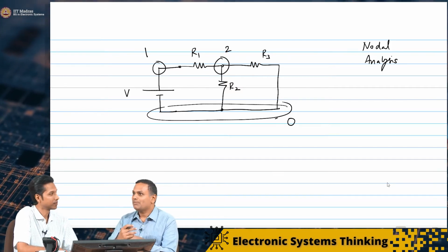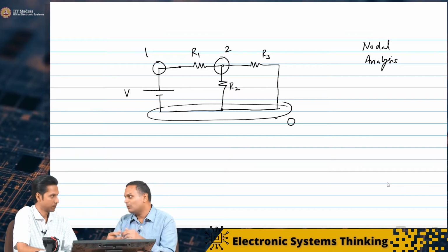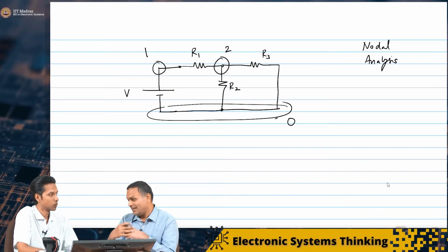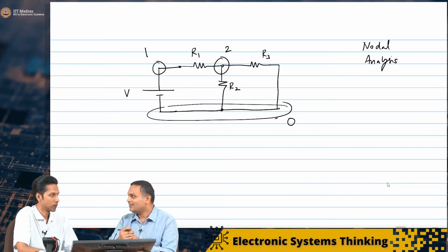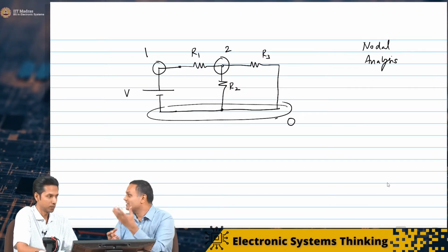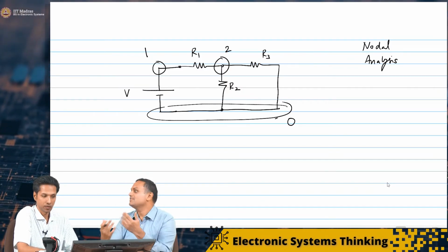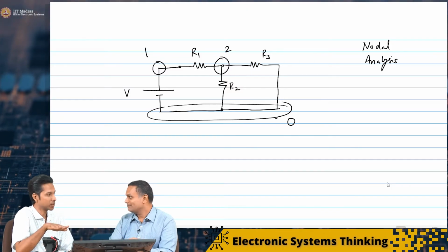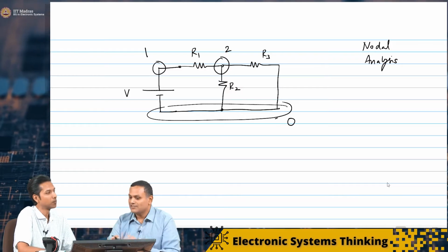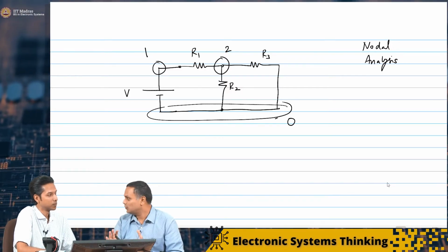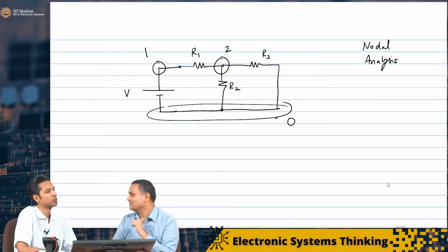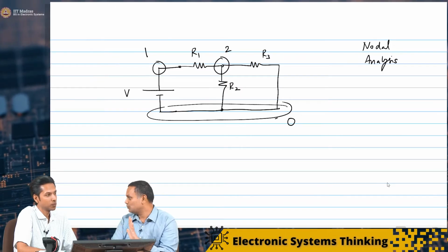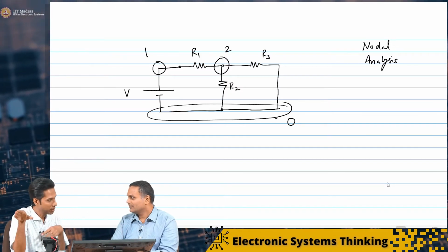Yes. So we saw that there were higher potential nodes and lower potential nodes, and if your potential increases at a particular point, that means that more positive charge is being added. If the potential decreases, charge is being removed. So our assumption is potential is staying the same, so the charge is constant. We are assuming that there is no net charge being pushed into node 2, and no net charge being pulled out of node 2. Means some charge is coming in, and the same amount is leaving. Correct.